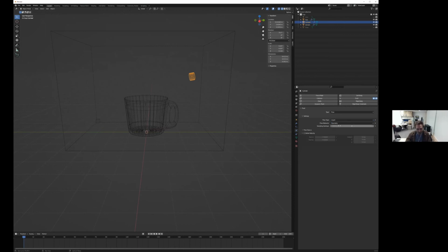And the flow behavior, if I just do geometry, it's just going to take that geometry of the cylinder that I added and almost use that as the container of the liquid. But I want the liquid to continuously flow throughout the frames. So I'm going to do inflow because that inflow is just, it's flowing inside the domain. Hopefully that makes sense. And I think that's good for now.